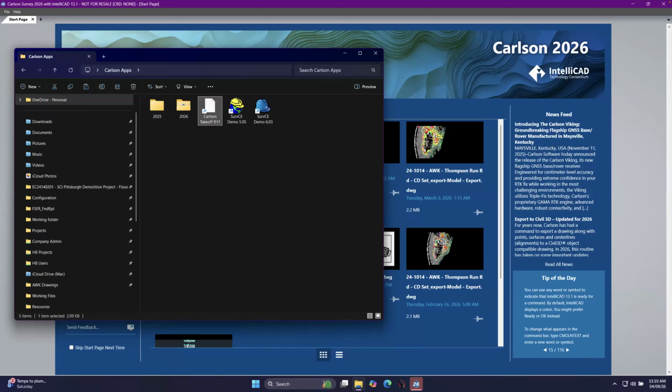You'll get the subgrade as well as the top finished surface, and you can generate each one of those separately, so you don't have to do a dial down, because the subgrades aren't going to necessarily be uniform all the time. So you can get those independently. You just have to keep track of which surfaces you're using, put that on your equipment, have it go out there and do the grading. And then when you come back, you can do the checking once you're finished with your finished grade.